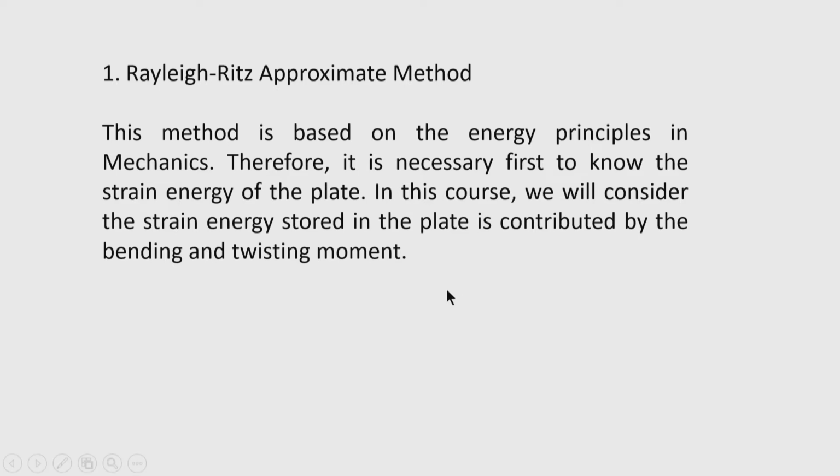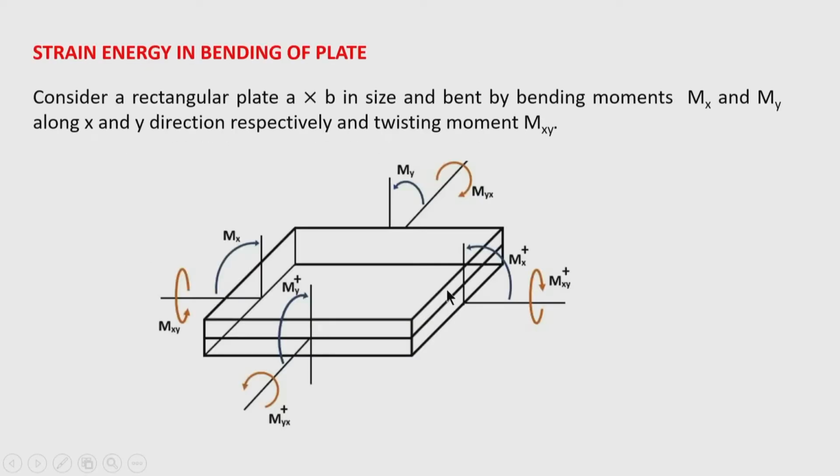However, the Rayleigh method does not restrict that one has to use only the strain energy expression for bending moment and twisting moment. One can include the shearing deformation as well as in plane forces also in the strain energy expressions. Okay. Now, let us see the strain energy expression for the bending of plate.